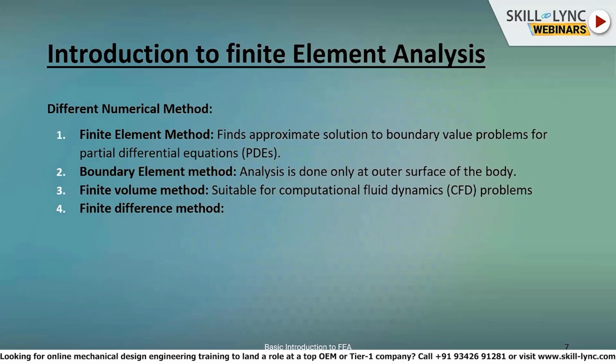We actually try to solve the partial differential equations in finite element analysis. In boundary element method, the analysis is done only on the outer surface of the body. The finite volume method is mainly suitable for computational fluid dynamics. And in the finite difference method we solve the differential equations, not the partial differential equations.